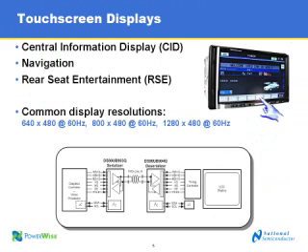And common resolutions there are 640 by 480 at 60 frames per second, 800 by 480 at 60 frames per second, and also 1280 by 480 at 60 hertz. Now, are both of these chipsets also right for touchscreen display as well? The 903, 904 is really targeted for touchscreen and displays. This is primarily because of the higher color depth that's supported, so most displays do require the 18-bit color depth supported by the 903, 904.